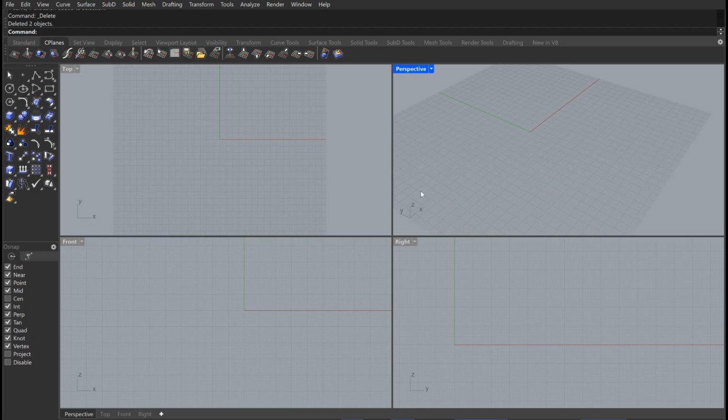Okay, now moving away from our 2D shapes, let's get on with our 3D shapes. We can access our 3D shapes from this tab over here. Let's say I wanted to make a rectangular prism, so press P over here so I can make it more measurable. Let's make this 100 feet, enter, let's make this 100 feet as well, let's make this 200 feet.